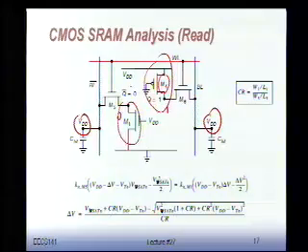And now I basically apply this and I raise the word line. When will the thing go wrong? What is the necessary condition for the cell to flip? That's what we have to think about. All right, so I have something which is VDD here. I have a node that's at 0. And now I turn this NMOS on and this NMOS on. If I take this little circuit, I don't care about this one because nothing will happen here. Right? This node is at 1. I turn on the transistor. This is 1. No current will flow. Everybody's happy. So on that side, nothing is really occurring. It's on the other side that we're worried.